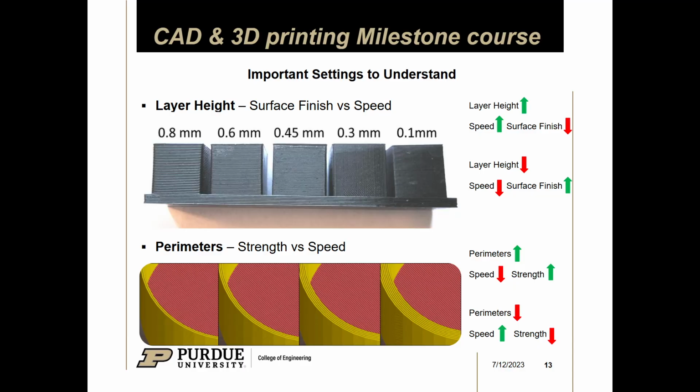If you want something to look super nice and almost unrecognizably 3D printed, you could probably go super fine, right? One drawback to printing super fine is that the parts are technically weaker, because one of the main failure points for 3D printed parts is one of the layers shearing from another one in the Z direction. Every time a layer makes a bond here, it's slightly weaker than the actual material itself. So if you print it apart and you hold it in this direction, it will probably break. And if you have more layers, then it'll typically get weaker. So for really strong parts, you might want to print at a coarser layer height.